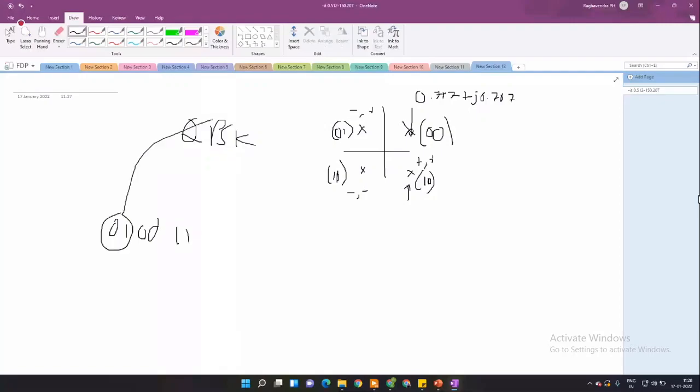So if I say 0 1, when I say modulation in terms of what I'm talking about in an SDR, I am simply converting it from 0 1 to minus 0.707 plus j 0.707. When I say 0 0, I am converting it to plus 0.707 plus j 0.707. 1 1 is minus minus. That is all I'm doing.